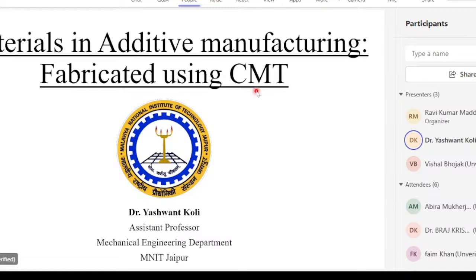The terminology cold doesn't mean it is actually a cold power source or a cold melt pool. It is a relative terminology as compared to conventional GMAW, as the parent technology is gas metal arc welding. The cold terminology in CMT refers to its low heat input.